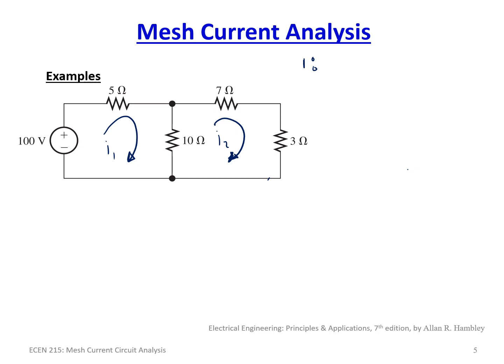So let's write that. First of all, we have this 100 volts coming in. But I'm going to save that to the end because we know that goes to the other side. So we'll start with the 5 ohm resistor. So 5 ohms times I1. And then we're going to have this 10 ohm meshed version. So we have 10 ohms, and we have I1 minus I2, the net current flowing through it.